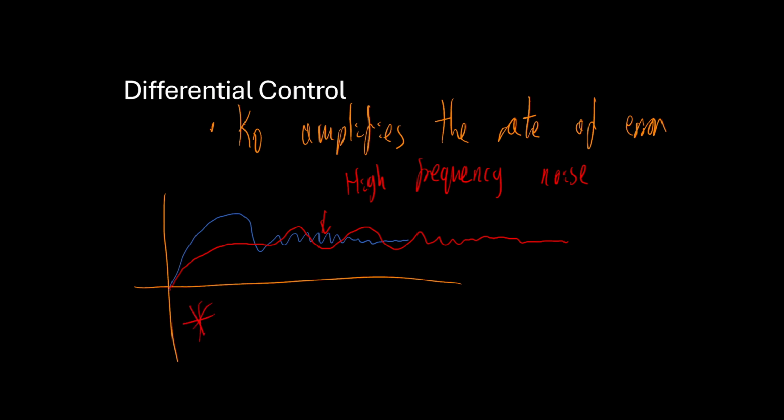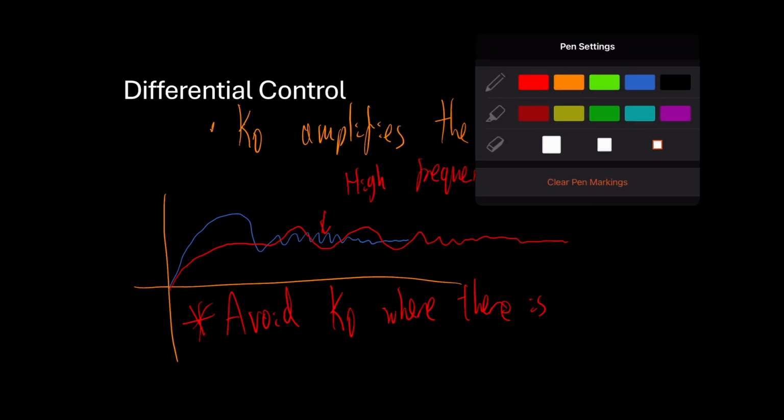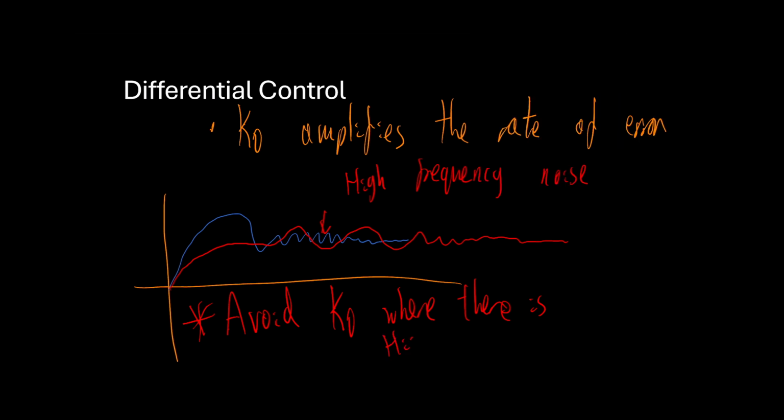So key point, avoid KD where there is high frequency noise. Be very careful with KD. It amplifies the noise that can cause instability, and your system will act erratically.